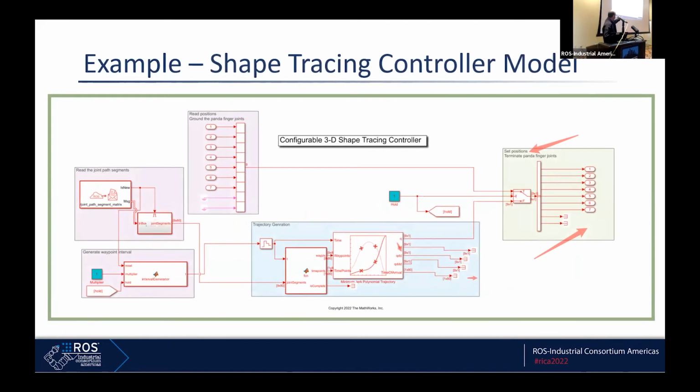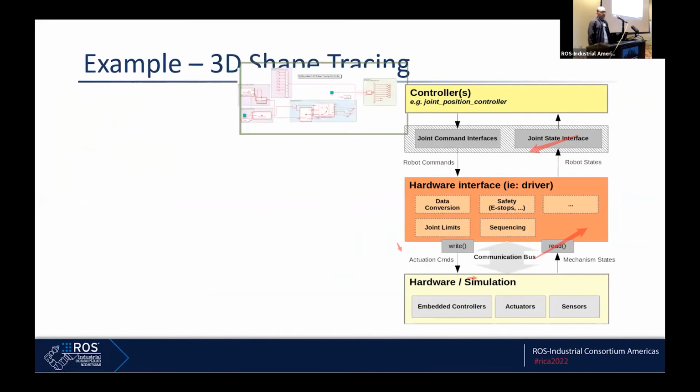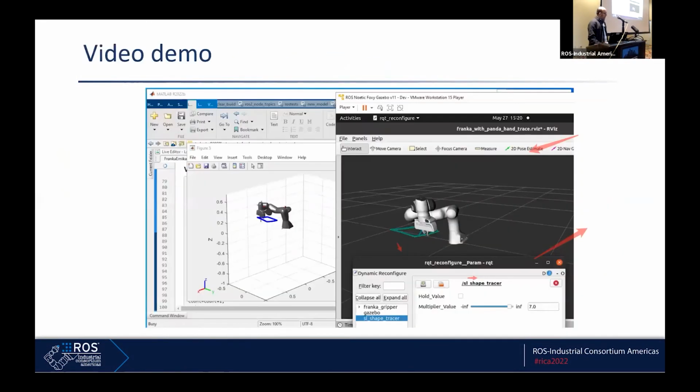As you can see, the blue part, the trajectory generation, stayed the same between simulation and code generation. That's the crux, basically the mind of your controller. Then we added some external interfaces that talk to the outside world. We'll talk about those later on. So you have your controller, and that controller you automatically deploy, and it can be run as a Simulink model on the hardware.